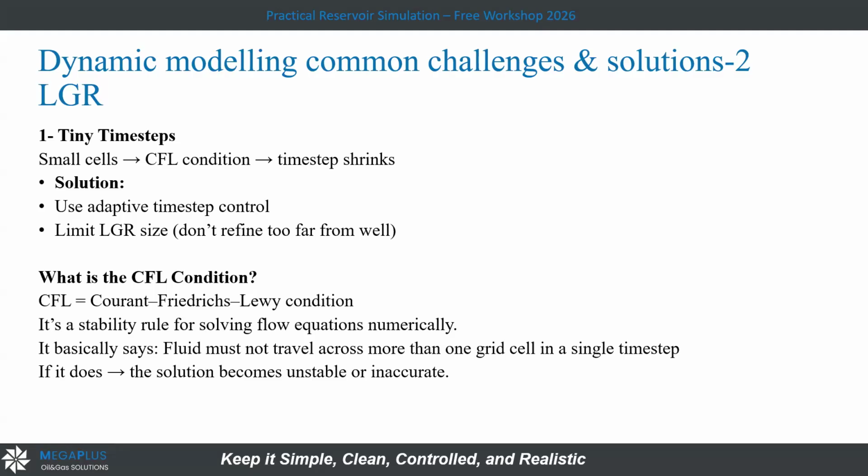This will cause an error. So according to the grid size, I have to run with a time step proper for this model. If I have a high time step and small cells, it could make an error. So the time step will not follow the flow of the cells. You have to take care about this if you are working with local grid refining.